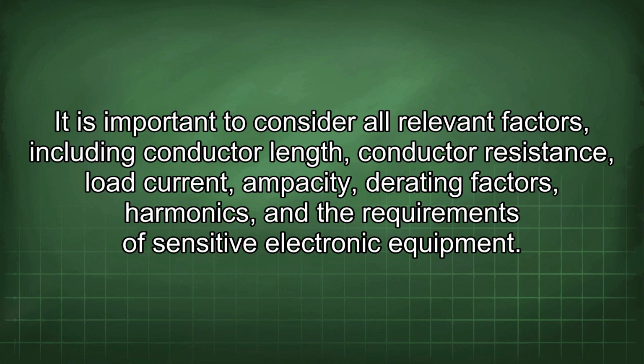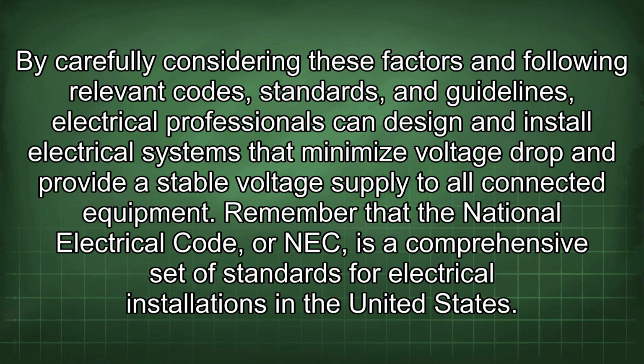It is important to consider all relevant factors, including conductor length, conductor resistance, load current, ampacity, derating factors, harmonics, and the requirements of sensitive electronic equipment. By carefully considering these factors and following relevant codes, standards, and guidelines, electrical professionals can design and install electrical systems that minimize voltage drop and provide a stable voltage supply to all connected equipment.